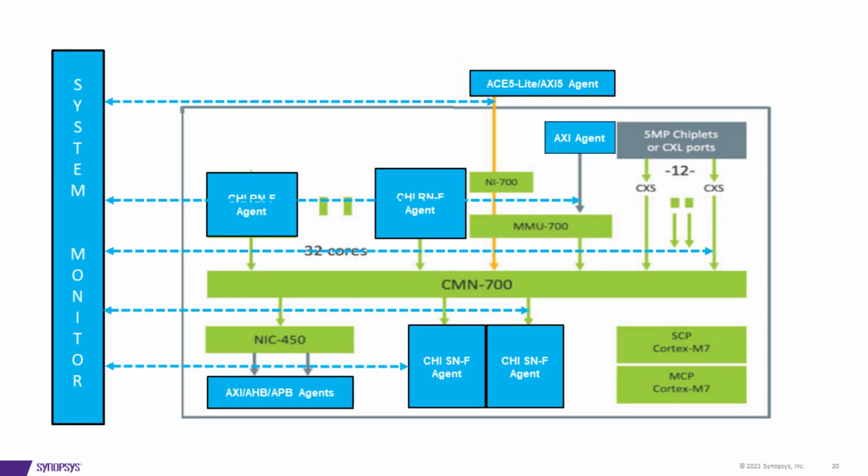So this is how a test bench will get generated using the VC Auto Testbench. It will basically instantiate the VIPs from Synopsys at every interface, depending on the scope where you want to instantiate the VIP. And then it does the checking at every interface. So this is how a system or a test bench will get generated, and you have the control to define at compile time which portion of the block you want to verify. Do you want to verify only a specific IP or the entire SoC?